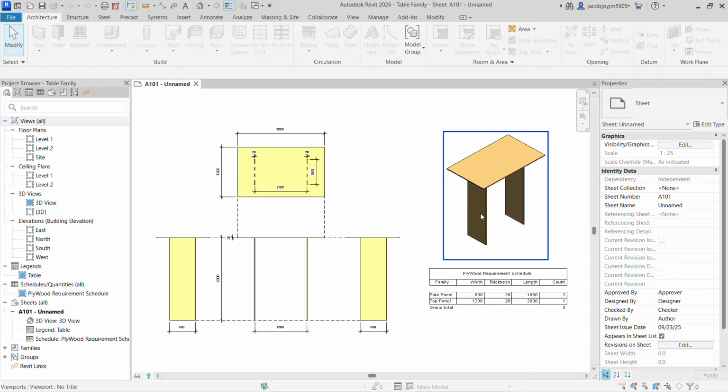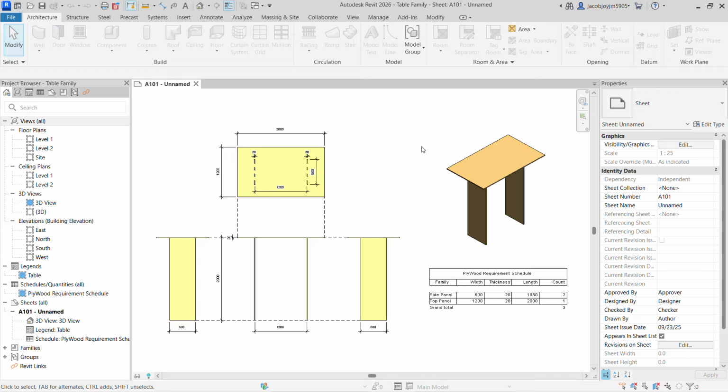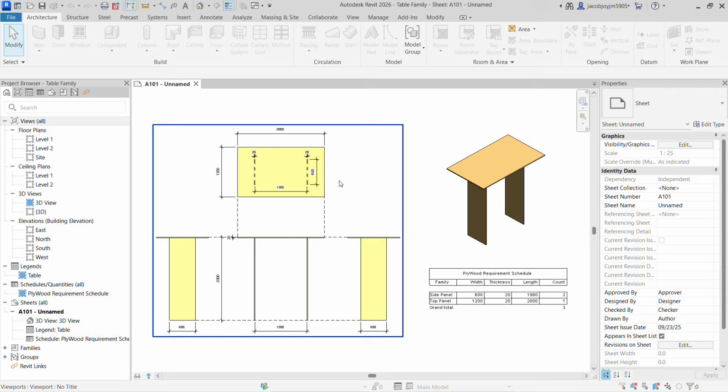After that, I have to assemble them in a parent family, another family. After that, I have to make each family as a shared family and I have to work with the parameters. Then finally, we will use it in project. Once everything is fine, we are going to create a schedule and detail legend drawing.